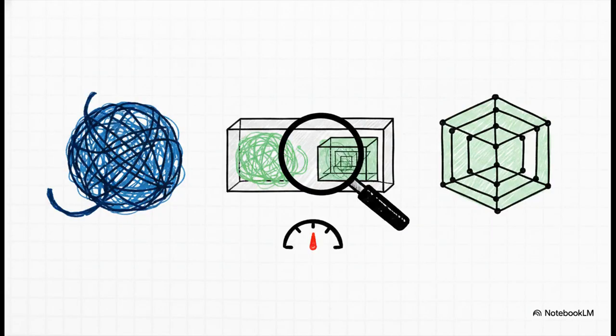You'll definitely want to jot this formula down. The exact percentage of crystallinity is what perfectly predicts a polymer's mechanical and chemical resistance. You can calculate exactly how ordered your material is with this. It's the sample density minus the amorphous density, divided by the crystalline density minus the amorphous density, all times 100.